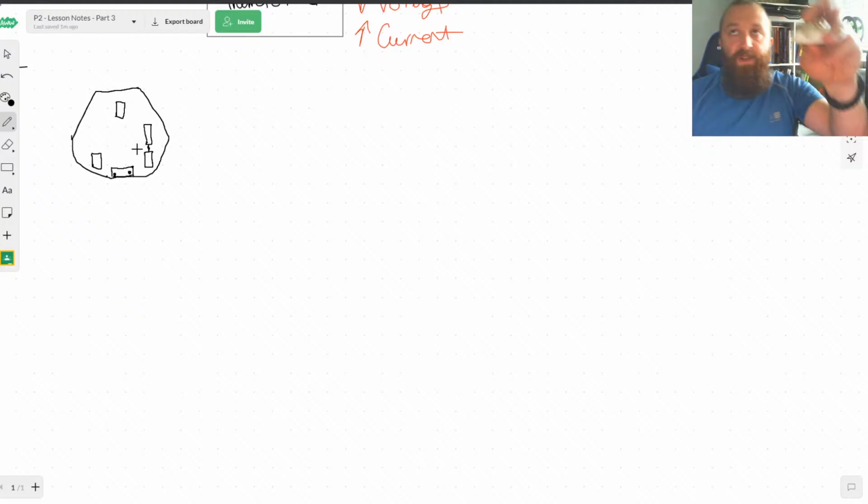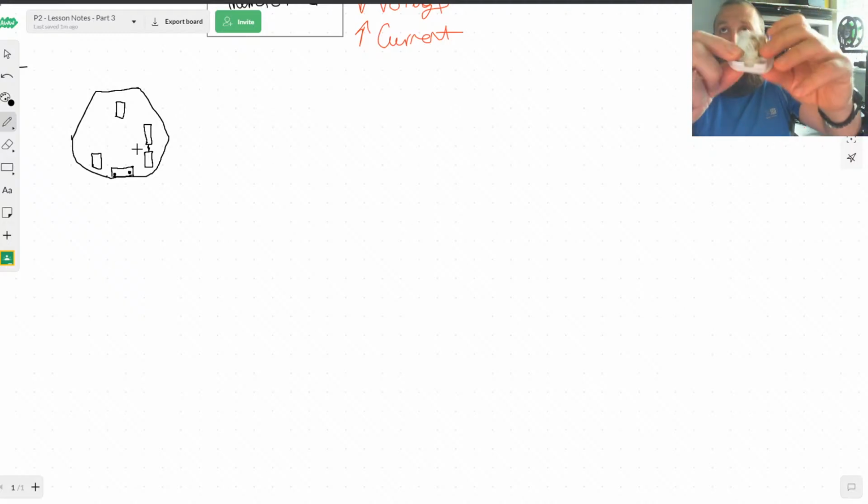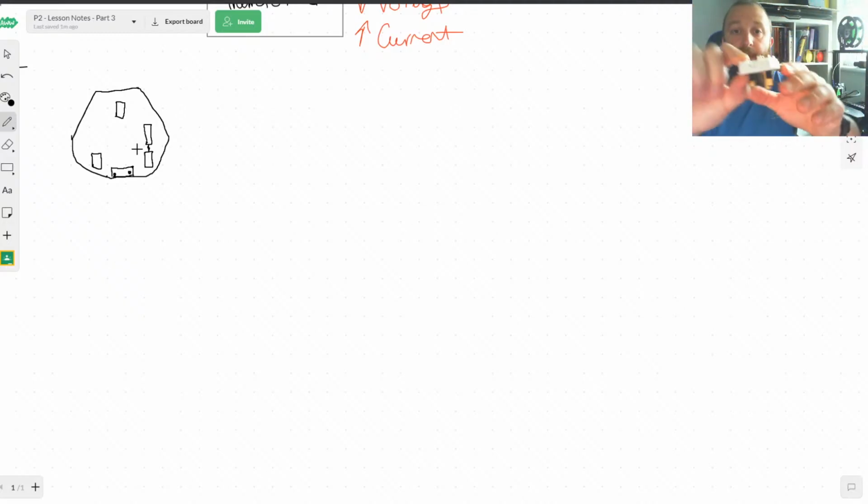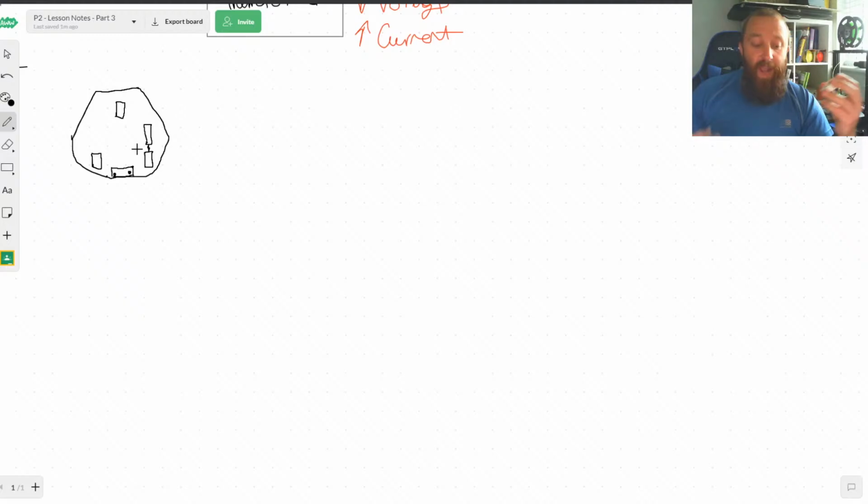So what we've got is this wire clamp at the bottom that I've just loosened off, and you'll notice there's a gap going in. Our wire, the electrical cable, goes in there, and the wire clamp clamps down to hold it into place. That just means if you've got something plugged into the wall and you accidentally knock it or trip over it, it's not going to pull some of the wire out and expose bare wires. So that's our safety feature number 1.